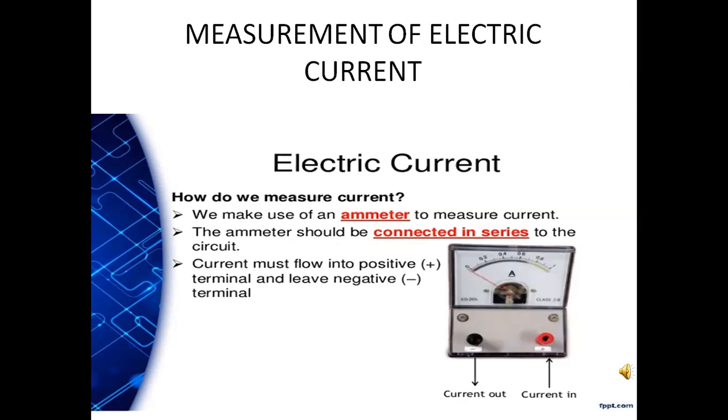The terminals of an ammeter are marked with positive and negative signs. An ammeter must be connected in series in a circuit. Instruments used to measure similar currents in the milliampere or microampere range are designed as milliammeters or microammeters.